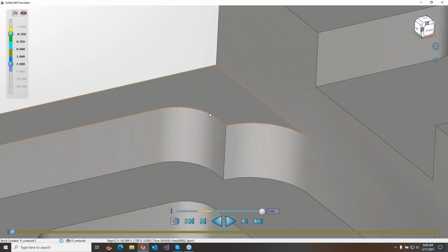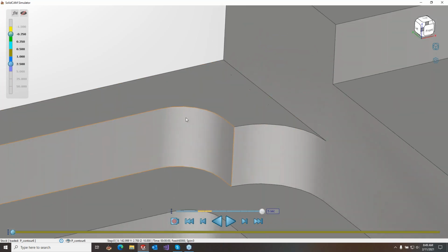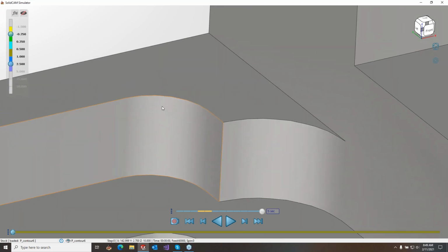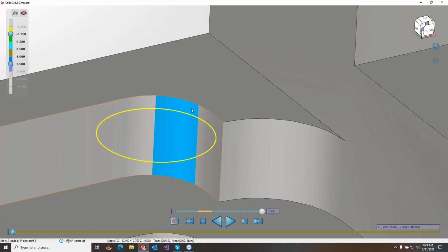A special measurement to do is measuring of arcs. And this has a special way to measure arcs where we have to highlight 3 consecutive faces. And this is because in SolidVerify, everything is triangulated. There is no actual arcs. Everything is faceted data, something similar to an STL. So if I hold down Control, I can highlight 3 consecutive faces. And you'll know you have an arc because we draw this diameter in yellow. And then you'll see down here, you'll get the vector, and you'll also get the radius, which in this case is 10.1.